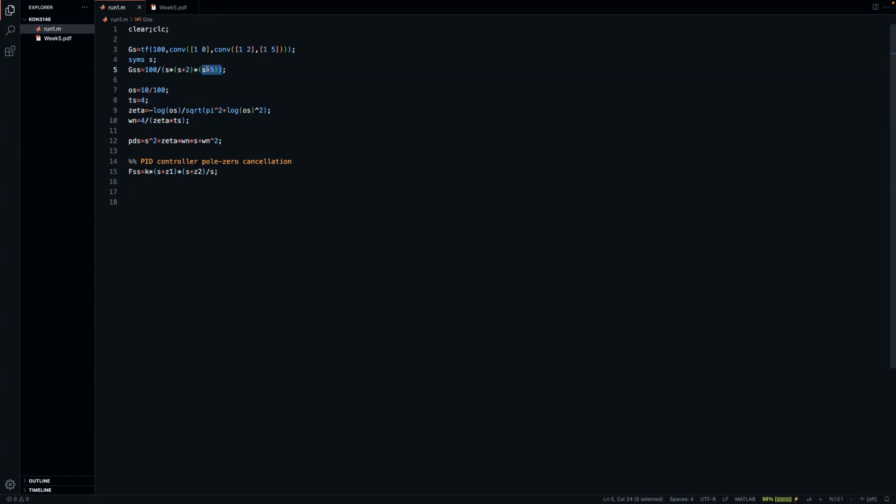If I do that, I'll get rid of that. And if you look at the root locus of the remaining part, you will see that it would be S and S plus 2. Then we will have another S, and we would add a 0, etc., etc. But sometimes when you look at the poles, you might want to get rid of some of the poles. And yeah, let's, for example, try to get rid of 2 and see what happens, because we will add a 0 and stuff like that. But we decide on the 0 of the controller beforehand. So I'm just going to choose this as S plus 5.